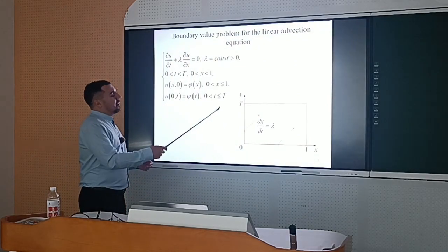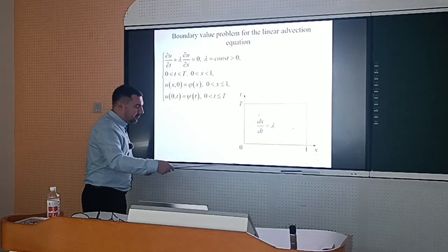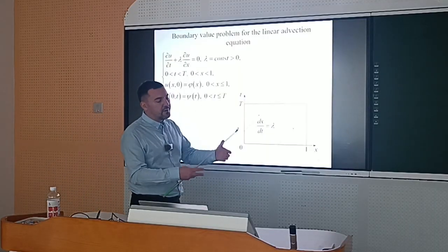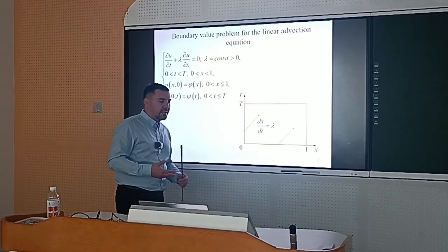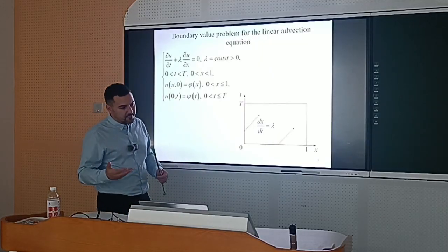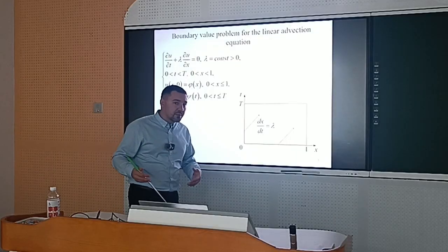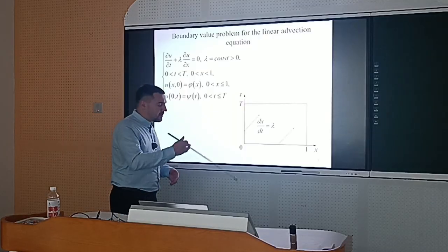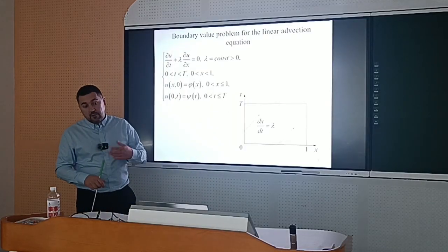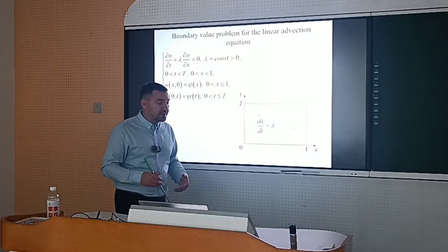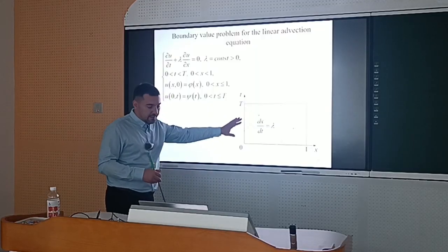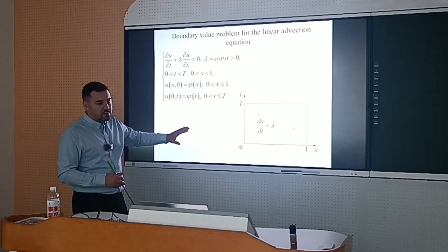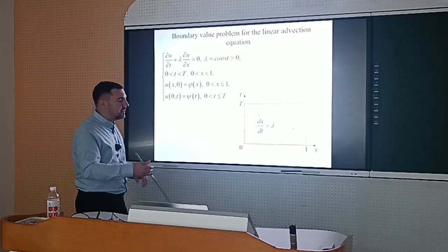For example, this is also the model situation for a much more complex situation when we are going to solve the Euler equations. For the Euler equations, the flows can be subsonic or supersonic, and depending on the velocity of the flow at the boundary, we also need a different number of boundary conditions, and that's a much more complex issue. And this is the simplest explanation. Why is it so? Because of the nature of the solution and the mechanism of propagation of waves in this model.